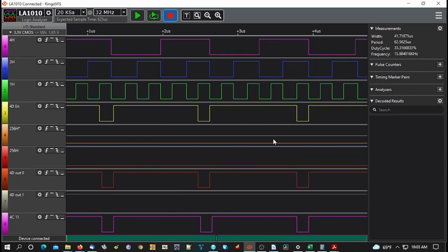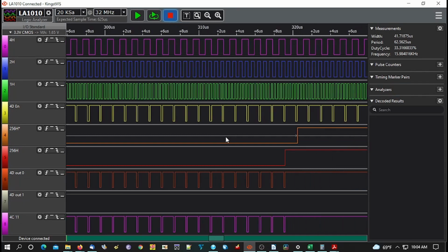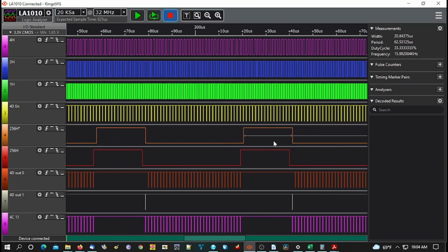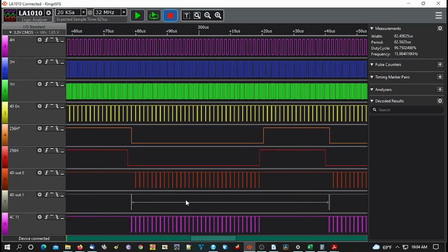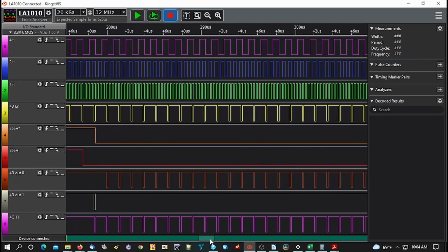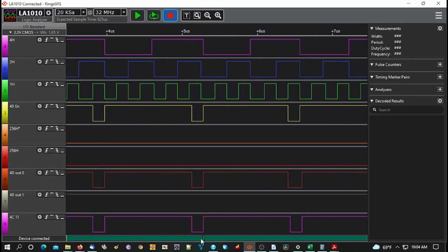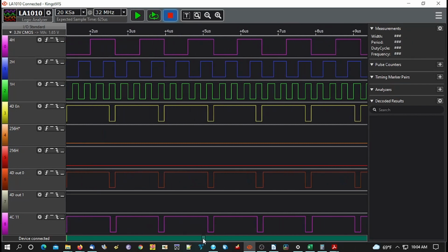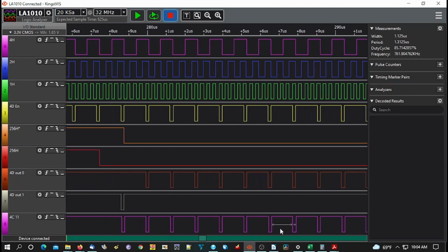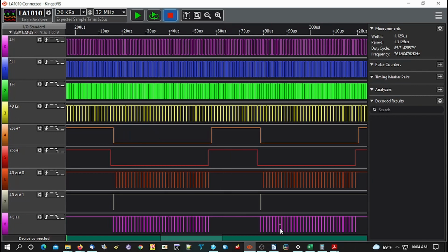Here we've got the logic analyzer hooked up to the main timing trigger. The main outputs are the 256H, which you'll remember is the H-blank signal. The final output to the 4C chip, pin 11, is a negative pulse for every new character load period. It's the trigger for loading the next character block into the parallel shift register and loading the next color ROM info.